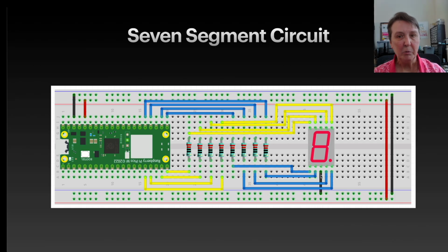And that doesn't work well if you're lighting all the LEDs simultaneously. If you have an 8 with just a single resistor versus a 1, you're going to see a difference in brightness because you're using one resistor for 8 LEDs at a time. So I guess the potential to burn them out might happen as well.